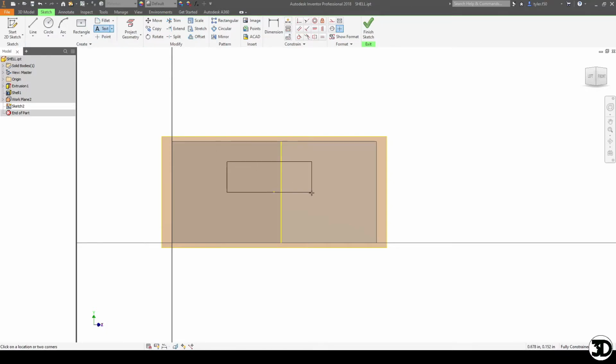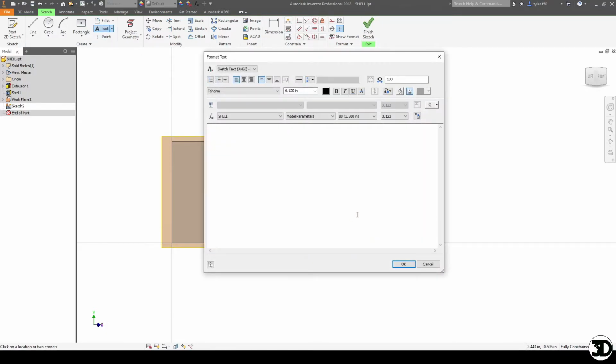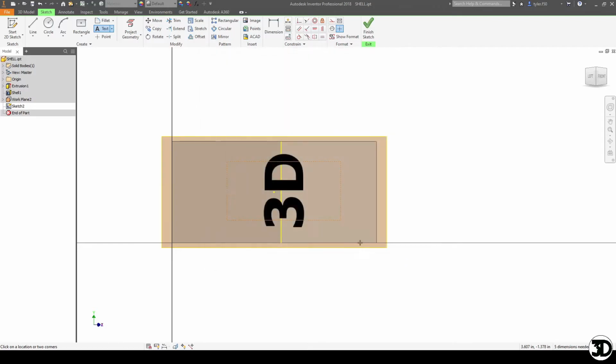The one thing I really like using for emboss is text, because sometimes certain fonts will not register when you do the extrusion feature. So then I would go to my default, which is the emboss feature. Sometimes you have to play with it either way, but at least it's a good start. Next I'm just going to put my text in here. I'm going to make it 1 inch font height, bold, and I'm just going to make it so that they're both centered.